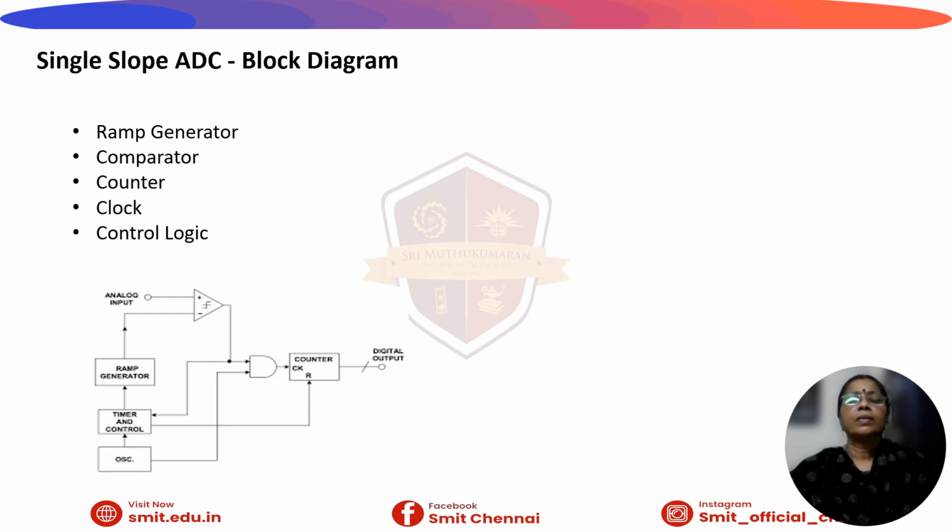The single slope A to D block description is given in this slide. The core blocks of the single slope A to D are ramp generator, comparator, counter, clock signal, and the control logic. It converts an analog voltage into a digital value by measuring how long it takes for the linearly ramped reference voltage, which is similar to a sawtooth waveform, to match the input voltage.